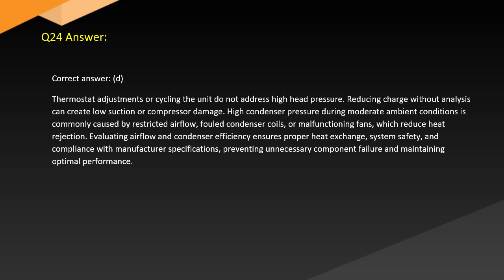Answer. Correct answer: D. Thermostat adjustments or cycling the unit do not address high head pressure. Reducing charge without analysis can create low suction or compressor damage. High condenser pressure during moderate ambient conditions is commonly caused by restricted airflow, foul condenser coils, or malfunctioning fans, which reduce heat rejection. Evaluating airflow and condenser efficiency ensures proper heat exchange, system safety, and compliance with manufacturer specifications, preventing unnecessary component failure and maintaining optimal performance.